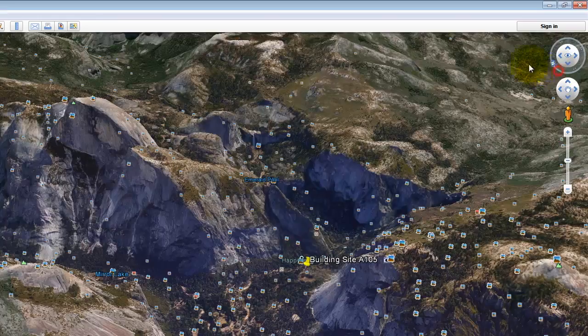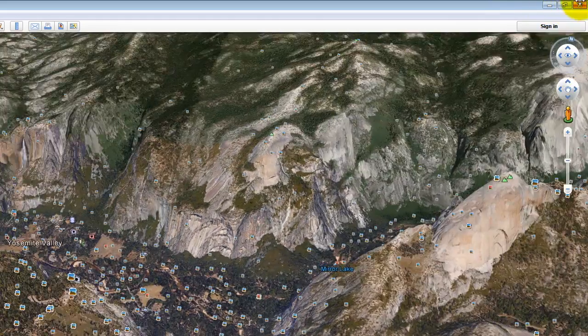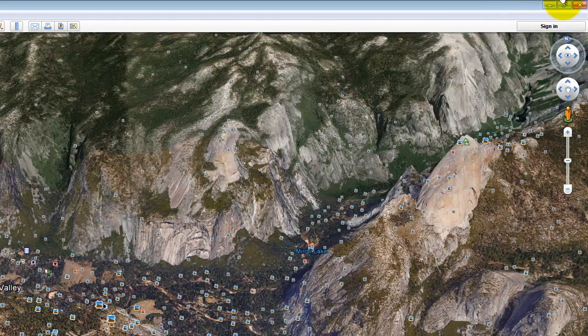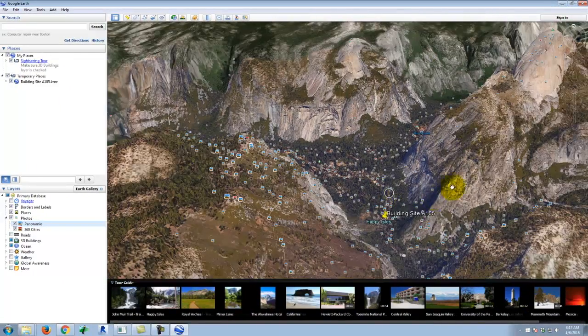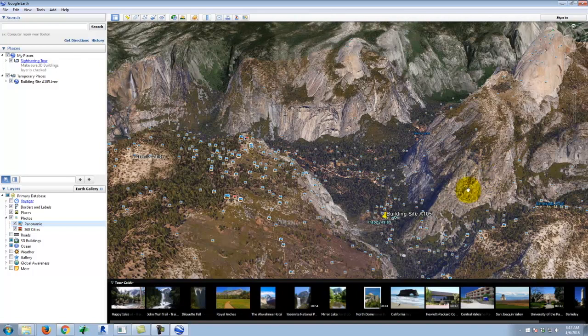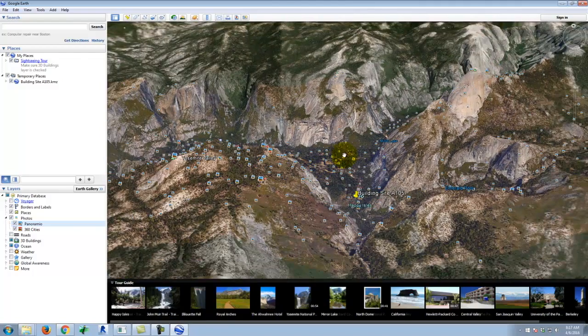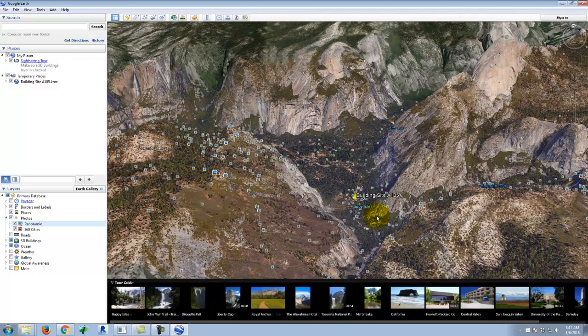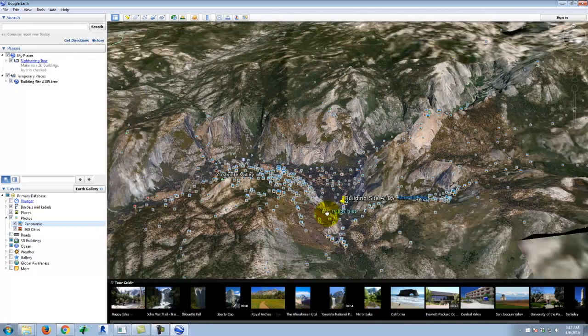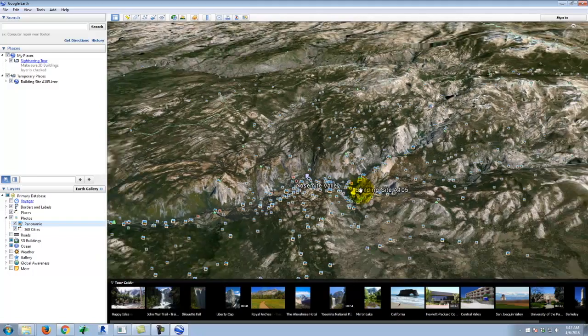In terms of orientations, north would be this way. So we're essentially facing north in this little valley looking off that direction. So the south light is going to be rather limited because it's between these two mountains as you come through, so you're going to get it toward the middle of the day. In terms of prevailing winds, you're going to get a wind up canyon during the mornings and down canyon at night. But it's relatively sheltered because it is down in Yosemite Valley.